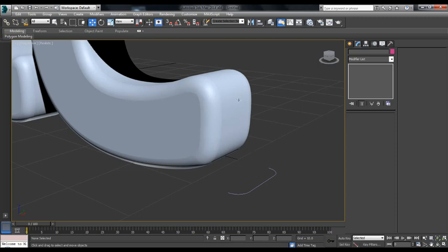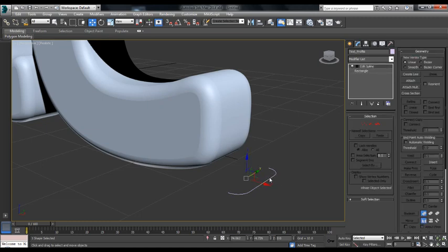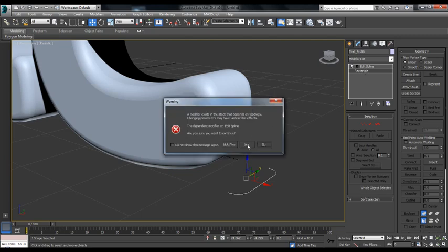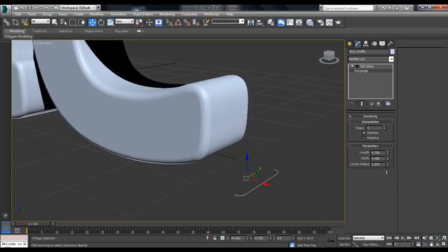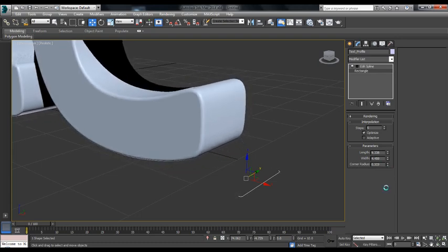But the main thing why I like this method is that if I choose this rectangle, which is now our text profile with a portion deleted, I can come down to this rectangle object, just hit yes here, we'll not worry about that dialog for a minute, and we can go down to corner radius, and when we change the corner radius, the text automatically updates.